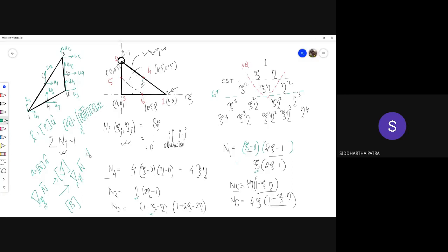Now this d omega is essentially the thickness, dx dy times h, which is the uniform thickness, and that can also be written as det J times d xi d eta, which should eventually be integrated through a double integration. So this procedure is very simple and very similar.